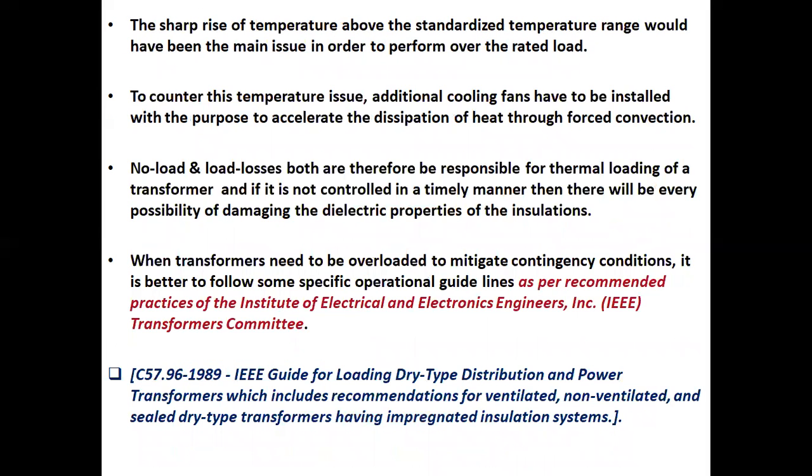The sharp rise of temperature above the standardized temperature range is the main issue when operating above the rated load. To counter this, additional cooling fans have to be installed to accelerate the dissipation of heat through forced convection.